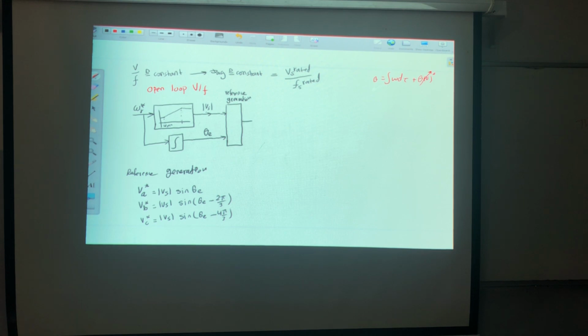Now after that, I'm having here what? I'm having references, 3 phase, 1, 2, and 3. This means that this line contains VA as a reference, VB as a reference, and VC as a reference, correct? Now, what I need is to translate this control signal into a power signal. You know, this is a control signal. It cannot operate the machine by itself. It has low power. It's impossible to feed the machine using this control signal. So I need a mechanism in between.